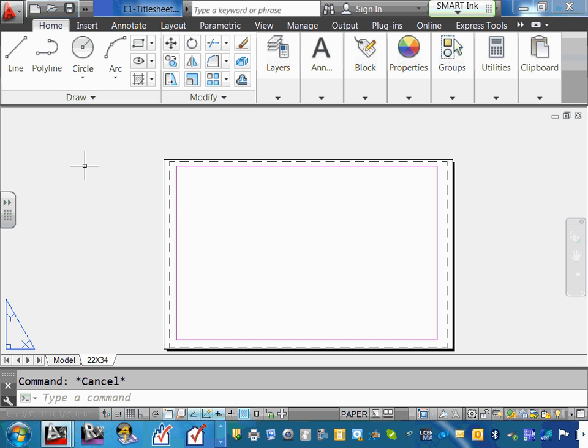Very important. When you work with CAD, you have to work with XREF. When you work with Revit, you have to work with links. They call them links. Exactly the same thing, guys. It allows the architects to modify their file, and at the same time, every time you work on your own file, you can see what they're doing. You can load what they're doing, and you see it. That's very important. What you can't do is you and the architects work in the same file. They don't want you to work in their file. But at the same time, you need to know what they're doing. The only way you can know what they're doing is by either XREFing in CAD or linking in Revit.